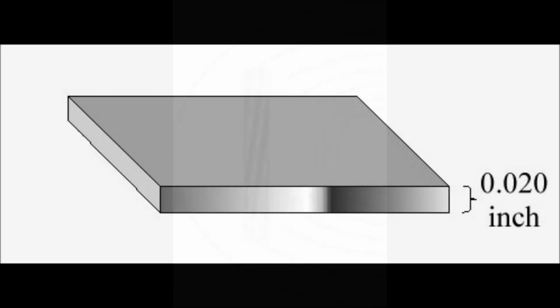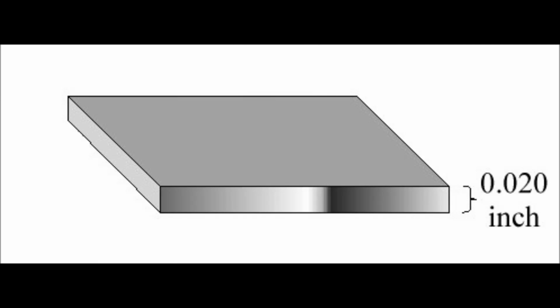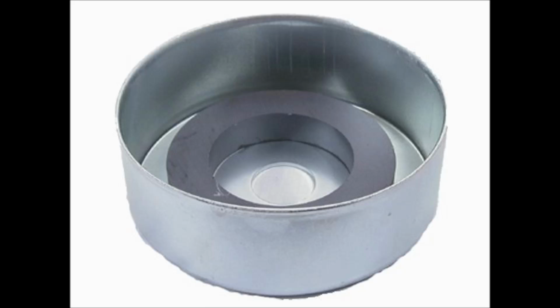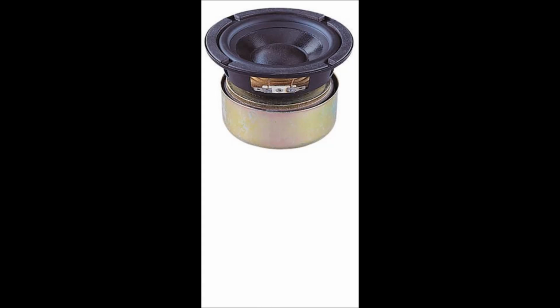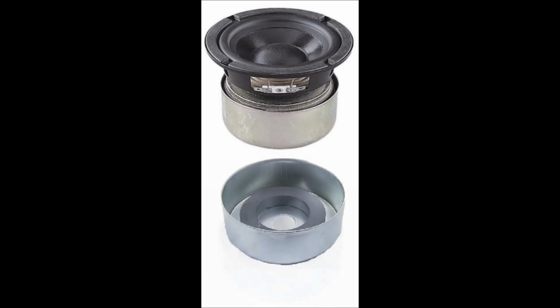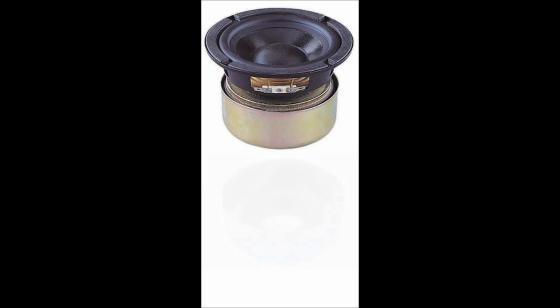A general recommendation for a typical application in a home environment, where one is shielding a circuit box with flat shielding, is to use at least 20 thousandths of an inch thick, high permeability material. A general recommendation for a typical speaker magnet application is to make 3 concentric cup-shaped shields from high saturation alloy. Use cardboard spacers between layers. Place the stacked cups over the back of the speaker magnet.